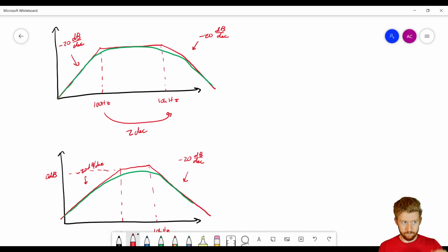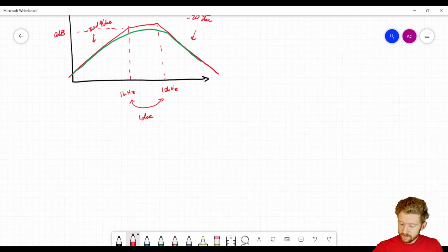This is pretty much all I wanted to say about bandpass filters, because they're either pretty simple or pretty complex. On the simple side, you can say that it's just 2 filters in series, but on the complex side, we would have to do a ton of math just to get the output versus input. That's something I'm not going to do because I think that would only confuse us. It would confuse me for sure. I'm just going to tell you, if it's closer than 2 decades, simulate it. So the next topic for today is higher order filters.